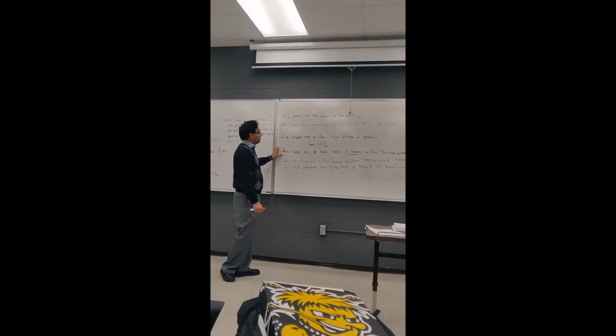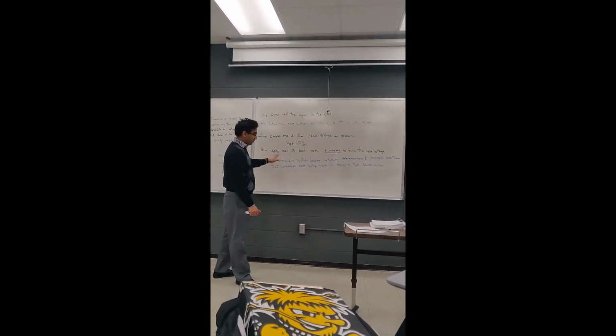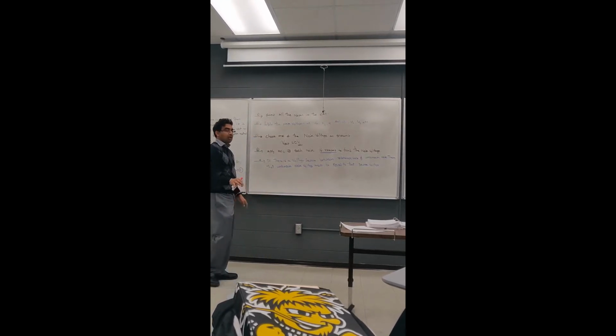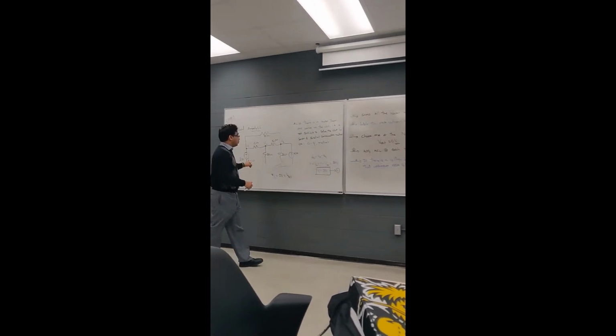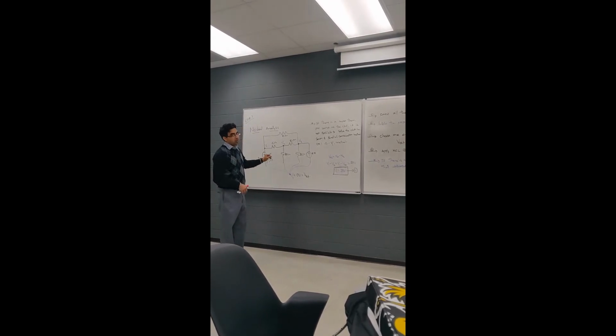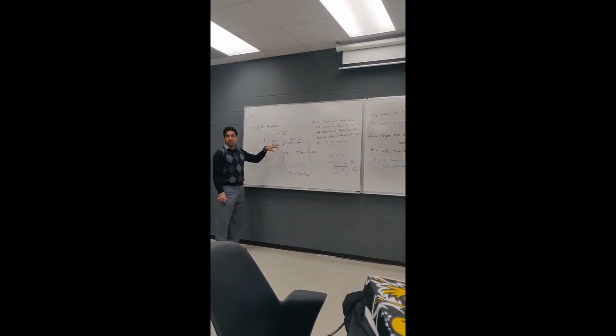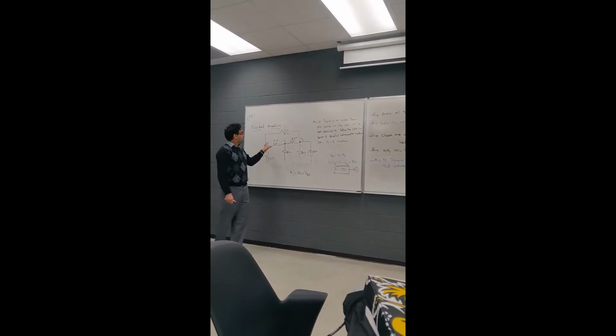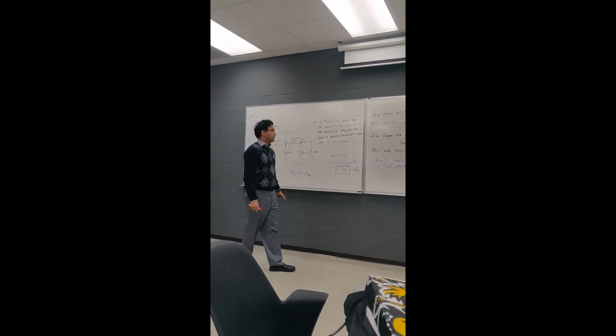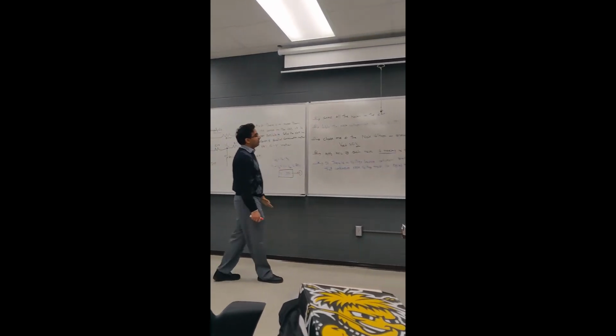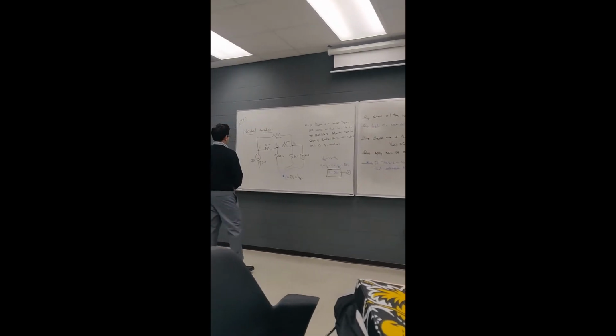Now step 4, apply KCL at each node if needed to find that node voltage. My goal in this problem is finding I1, but now I shifted my goal to finding V1, V2, V3 instead of I1, because once you find V1, V2, V3, I can find either current or voltage or power in any one of those elements. So now my goal is finding V1, V2, V3.